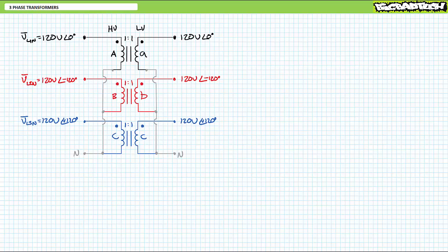configuration. As one might expect, if each of these now interconnected 1-to-1 transformers were being fed one line-to-neutral phase of a light industrial three-phase AC system, the secondary outputs would understandably be the same magnitude, yielding 120 volts at 0 degrees, 120 volts at negative 120 degrees, and 120 volts at positive 120 degrees. This being said, since we're illustrating each transformer as an individual entity, this diagram might be a little confusing given the overlapping wires. It doesn't clearly illustrate the Y with neutral shape we're going for.